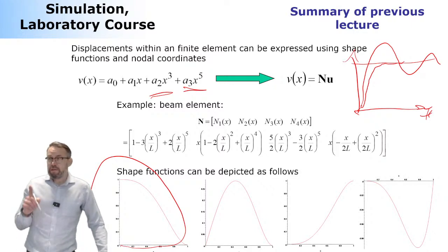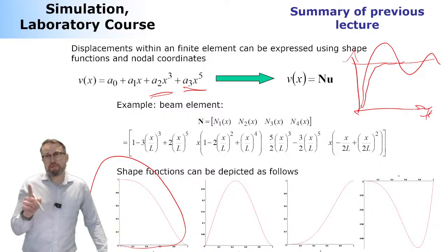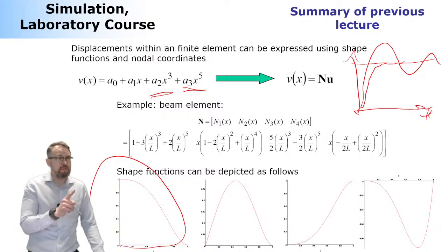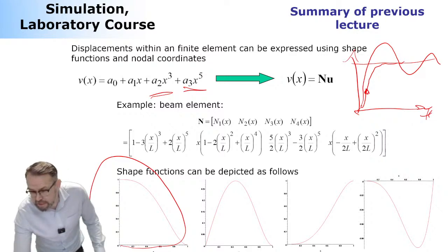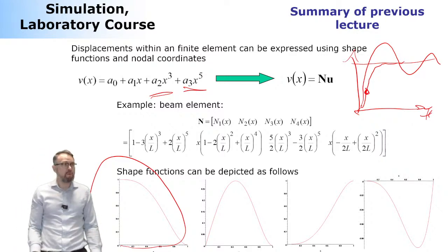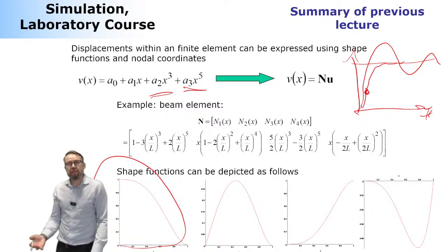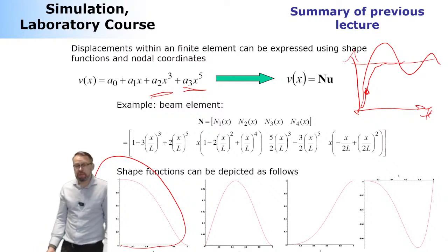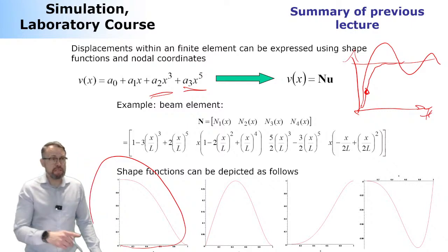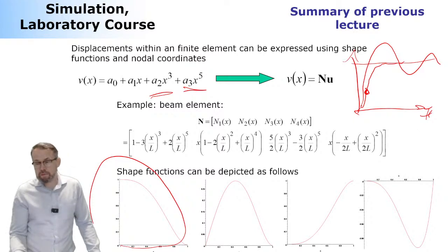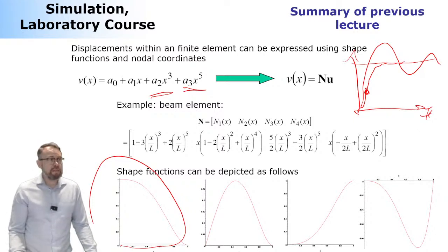And why not? Because for each finite element analysis you do, you should actually check whether or not your solution is converged. Because you may get a solution that is here that is really way off. This is simply way off because the amount of elements you have used is not sufficient. So what you should do is mesh your structure with 2 different alternatives, fewer and more elements, and if the solution is not changed, it's obviously converged. But if it is changing, you keep on increasing the elements until it's not changing anymore.